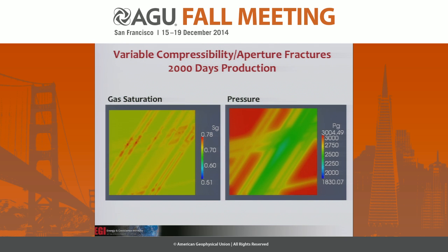So the final piece of the story is you have to take this information and actually include it in reservoir simulations. And this is just an example. The specifics are not important. The relevance is that the coupled characteristics that we talk about so often in terms of fracture mechanics have to be carried over into simulations that talk about how production occurs from natural fractures, in terms of fractures having finite compressibility, and that compressibility altering the production from individual arms, closing off certain ligaments of fractures so that this fracture pack, these fractures out here, may ultimately be completely isolated from a wellbore that's down here, strictly because of closure of communicating fractures.